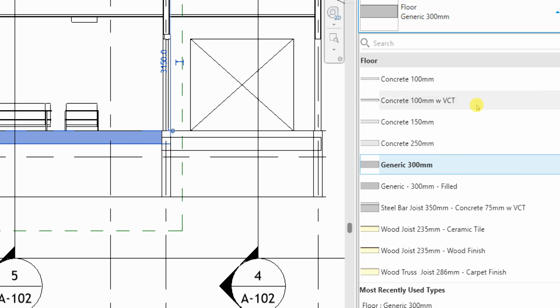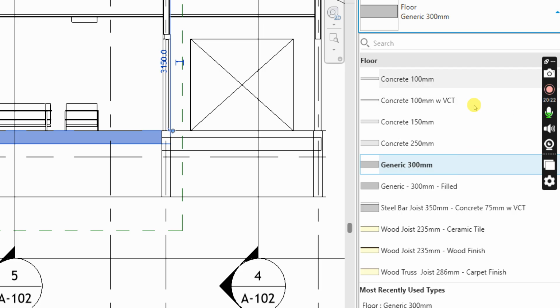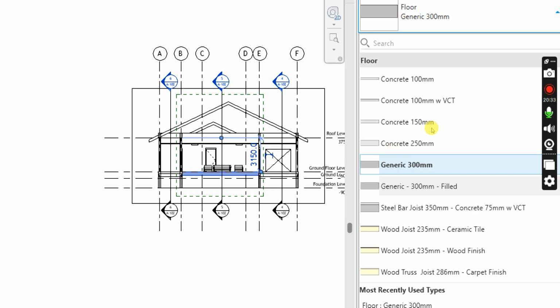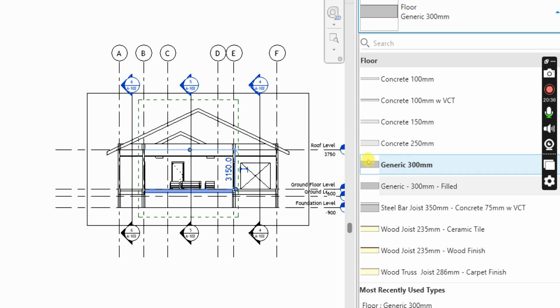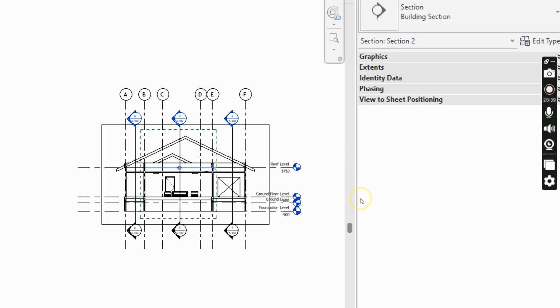If I wanted to use it as grass or as paving, even the paving, if I want to do vehicular pavement or pedestrian pavement, I'll take one of these, edit it, and then name it as such so that I can use it for that purpose. So editing elements is very crucial for you to create whatever you want to create. That's the point I want to make.